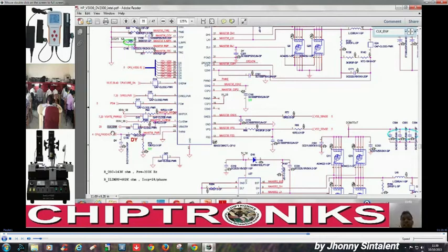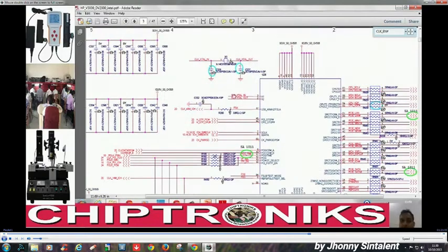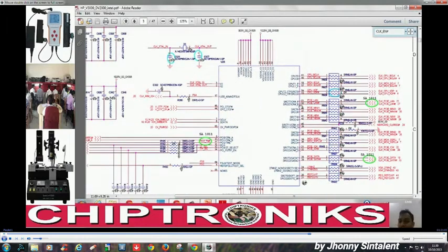So when my CPU core regulator starts correctly, it will generate the clock enable signal. That clock enable signal will help generate CK power good, and when it gets CK power good, my clock generator will turn on. It gets two signals, CK power good and STOP_CPU, that is CPU stop, along with supply and crystal, and then the clock generator will turn on and generate the required clock needed by the devices on the notebook motherboard.